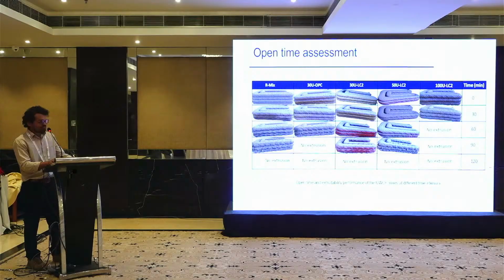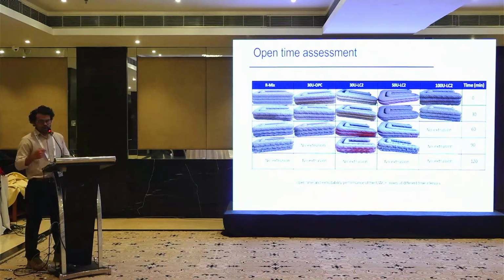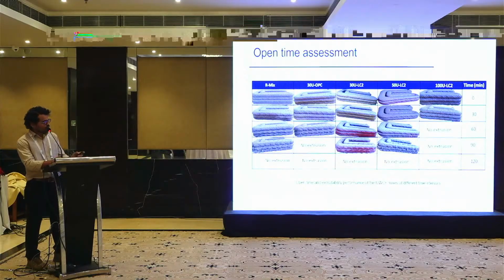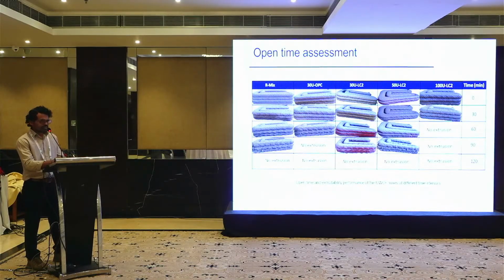I printed every half hour, because the open time is the duration during which the printer is able to print the material. So I print the material at different time intervals and see how surface defects form on the surface. Printing went up to 2 hours, and a few mixes were found not extrudable at around 2 hours.